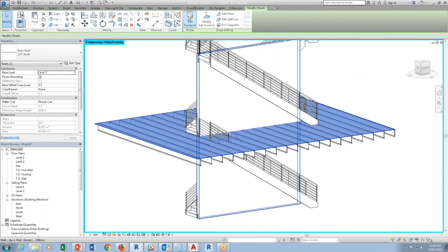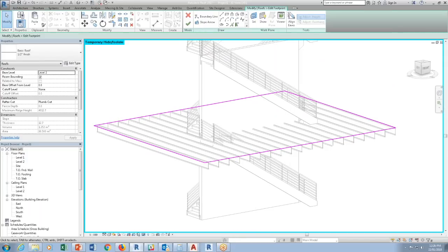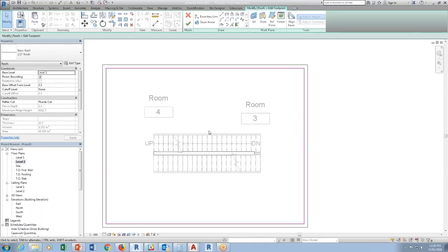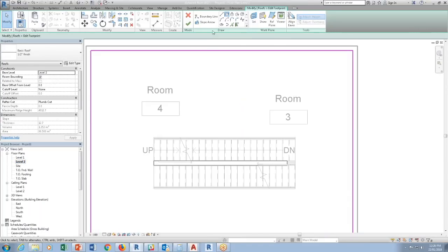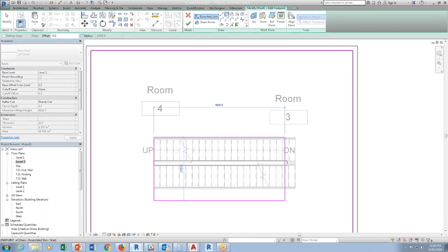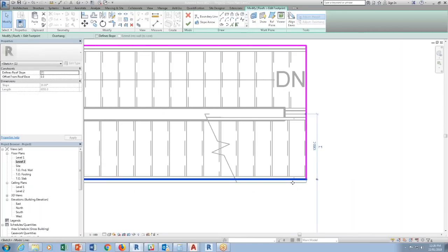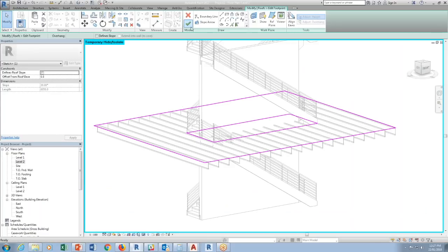So this is why, when you do a floor, I typically like to do finishes. I don't like to do structural stuff, so I use the structure to just display your object. If you want to poke a hole, you can also poke a hole. This is the nicest thing about putting in the beam system: you can poke a hole and it will understand where you want the hole to be.